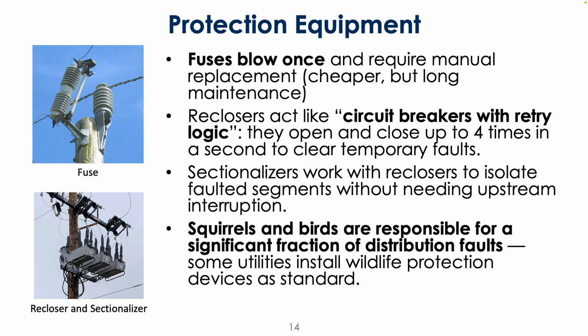When the recloser closes again, you go back to normal. The recloser isn't physically fixing the problem downstream. The hope is that the problem is a temporary one, so that by the time you've opened and closed it again, the fault is cleared and you're not damaging your equipment.